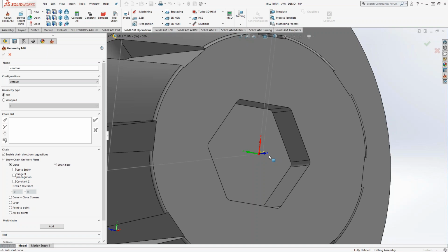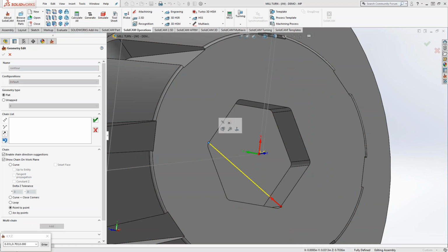And you can also, like Kevin said, set open edges. But let's say the slot is not there currently in the state of your operations. The slot eventually will be taken out. But if you have a pocket where the slot is part of the final target, but at this time all you're doing is that one pocket, how do you jump that corner? Always remember that you have the point-to-point option. You can actually go from one vertice to another. So you can actually close that pocket for you. So that actually ends up being a closed line.